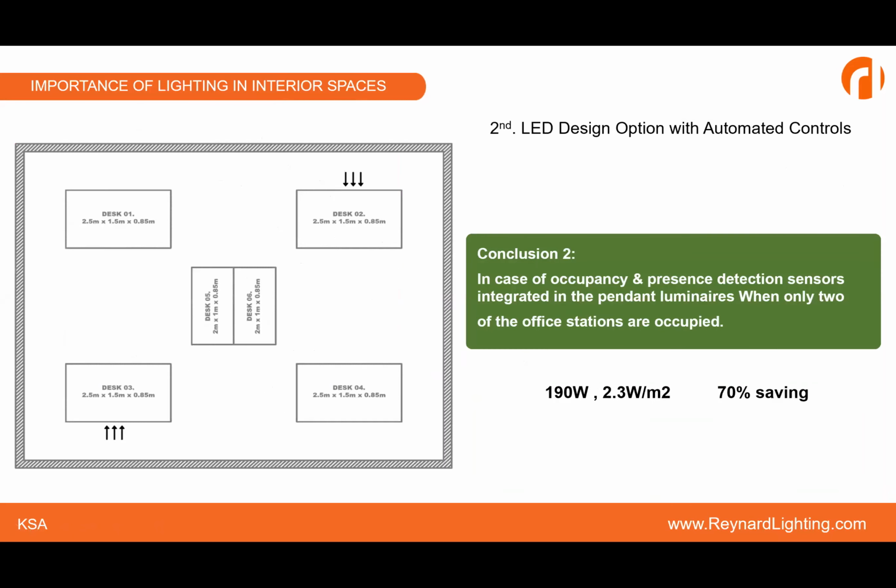Now we go further. So again, the same as the last scenario where I use downlights and a pendant light over each desk. Now, during the day, let's say during the lunch break, when people go out, if we are not implementing daylight, motion sensors or occupancy sensors, the lights will be on even when there is nobody using the space or even sitting at the desk.